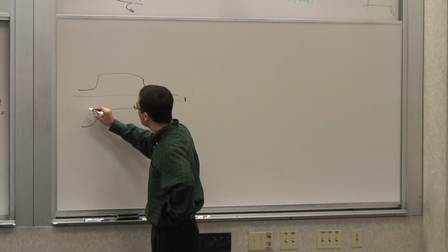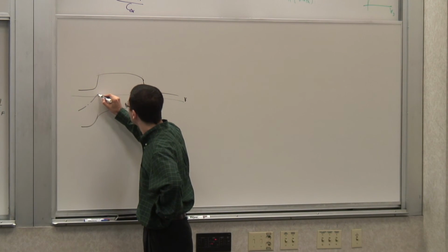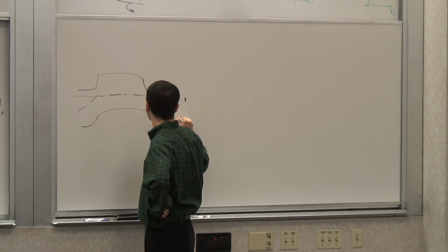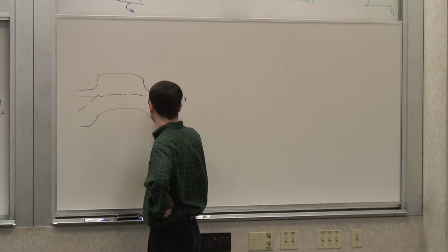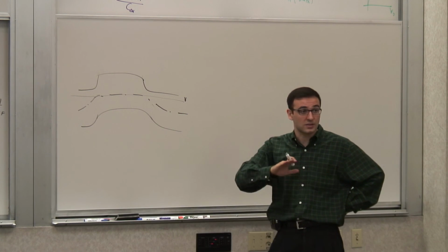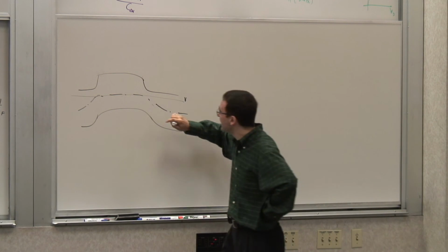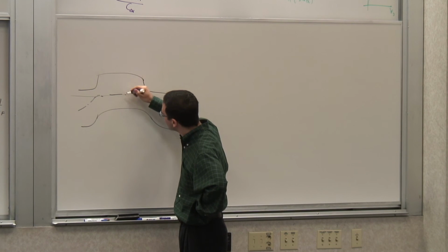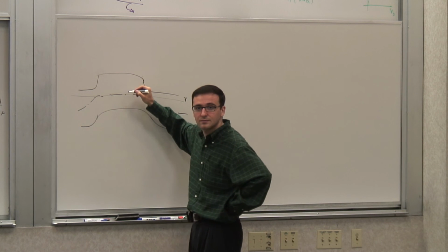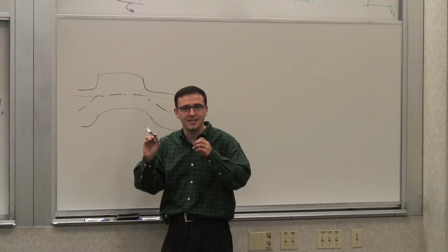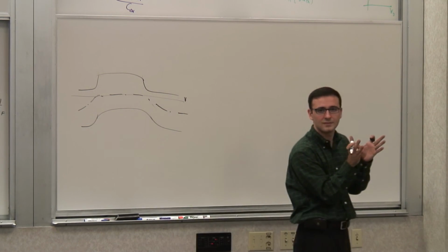And at some point, if you look at EI and EF, then EI and EF will coincide probably. For some, the transistor is still not turned on, technically speaking, right? Because at that point, we are still far away from the concept of strong inversion, which is basically having the same amount of carrier that you had in the bulk before and after. So EI has to be below EF by the same amount that it was above, right? The VF. Now, but if you're at this point, this is the onset of inversion, any kind of inversion, right?